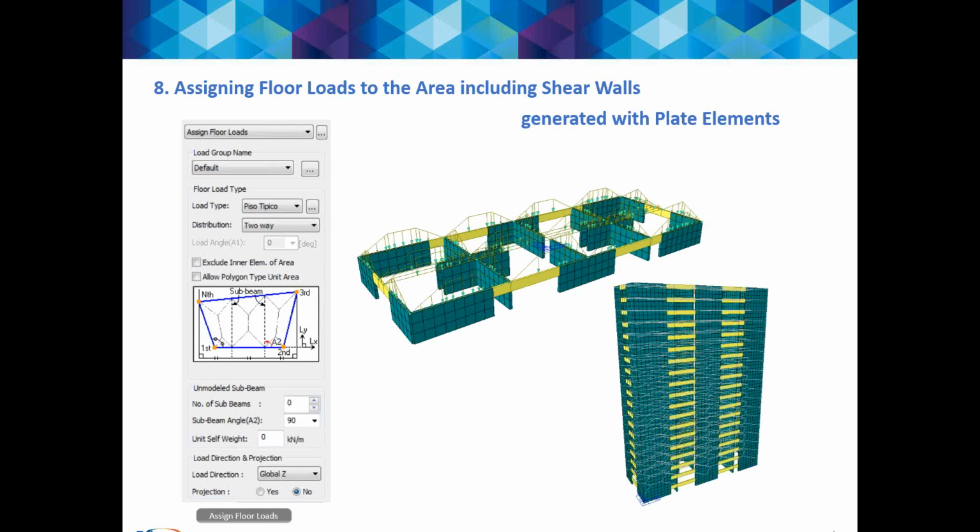And the other feature is the improvements in the floor load. Floor load is used when we do not model the slab using the plate element, and if we just use the floor diaphragm and apply the loads for the self-weight of the slab or the live load, this floor load is very useful. But this floor load can be applied to a closed area because the floor load should be distributed to the connected elements in that area.